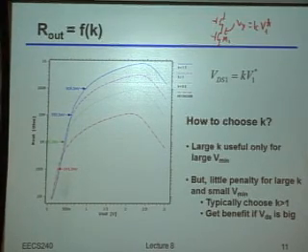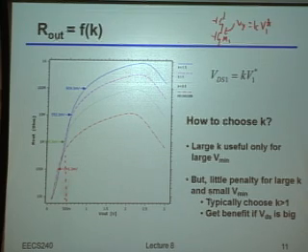Okay? And what we basically said was that below some certain drain to source voltage across that net cascode structure, it didn't really matter what choice of bias we used. We were going to get roughly the same output impedance overall. But as long as we got a higher drain voltage, then you would start seeing a big difference between the cascoded versions and the non-cascoded version. And more importantly, we said that if we had sufficiently high drain voltage, we would start seeing a difference between applying a larger drain bias across that bottom device versus a smaller drain bias.